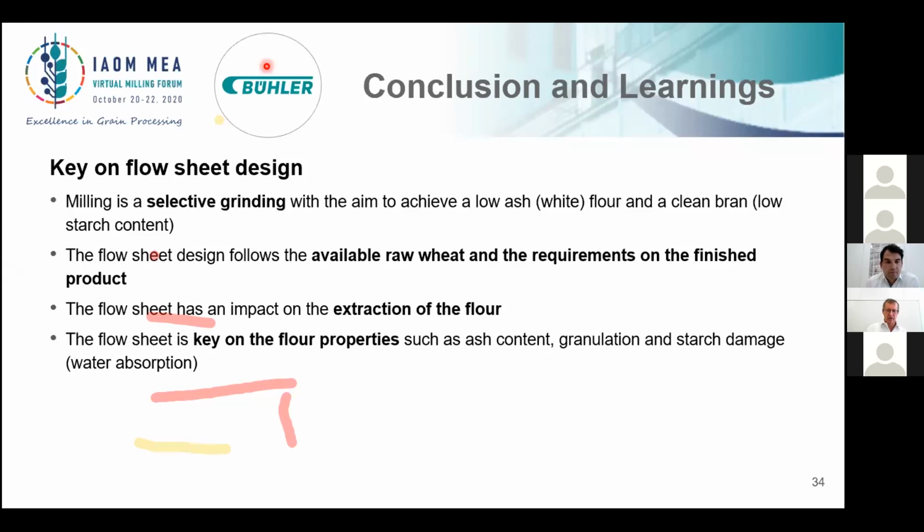Or you go to the extreme and you separate hard and semi-hard, you grind it and you blend the flour. My experience taught me that in most cases, separating the grain in cleaning is an advantage, and blending it before first break simplifies the process. So I would do that without blending the flour afterwards. Blending flour needs a facility, needs installation. If you have that, you can do that, but it should only be applied for the more extreme flour properties, like a very high protein or a different ash content.